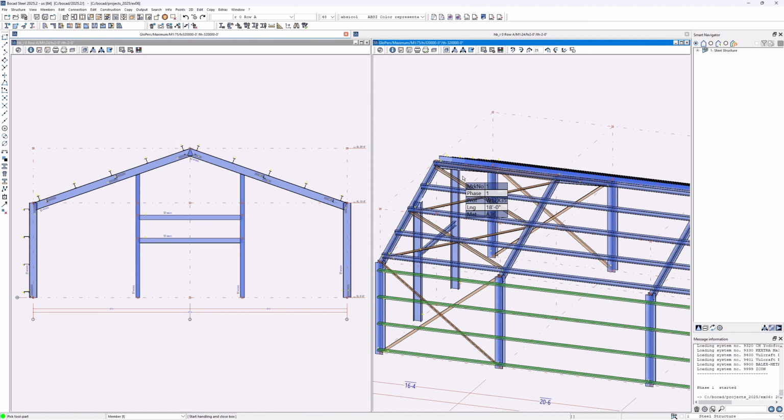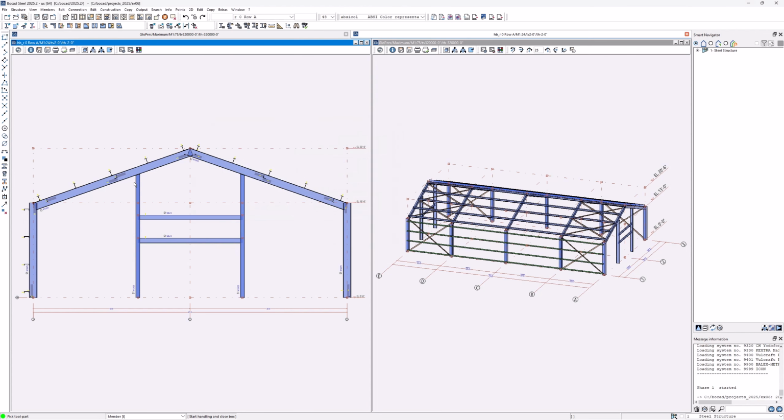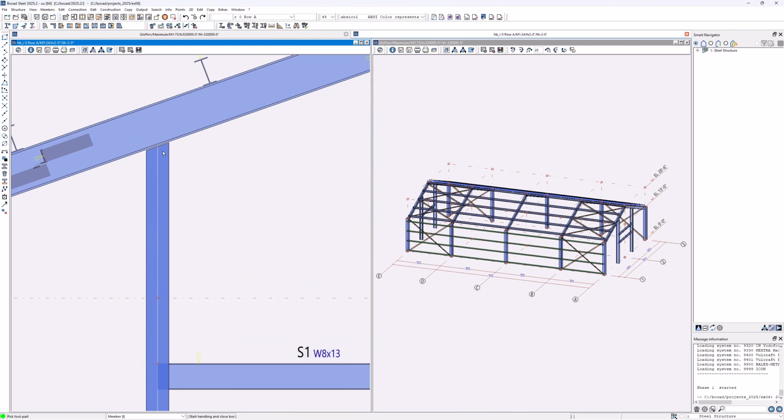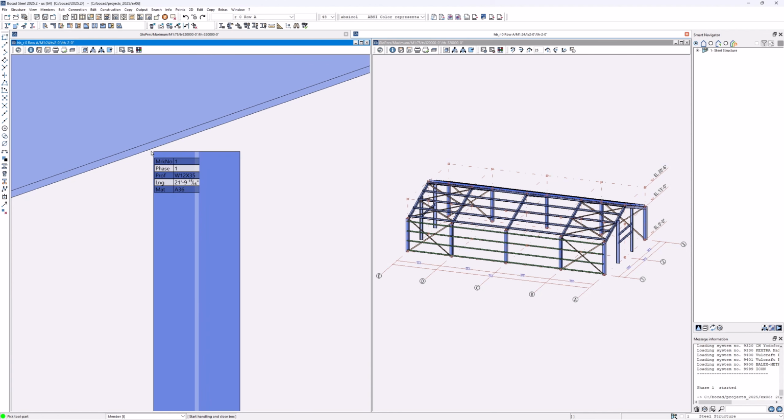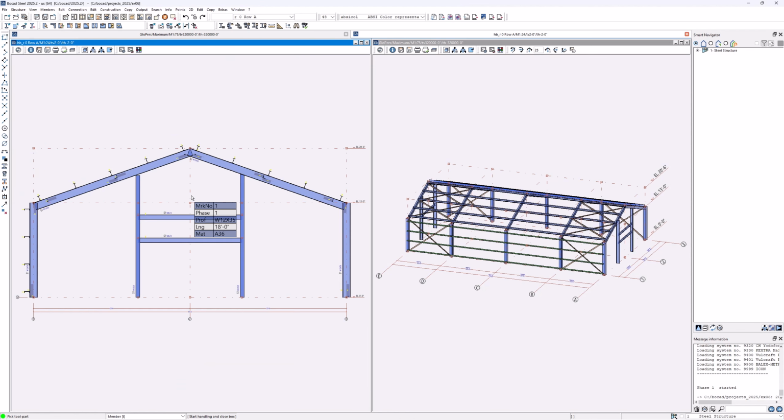This component adapts the column. I could also use perpendicular on axis. What does that do? Especially useful for bracings, but I could easily also show it over here. This component, enter, forces this one to change, enter. So we'll adjust it to the first contact point with the little gap, of course, but it'll be an orthogonal cut. So it's a bit like lengthening or shortening up to a certain plane.